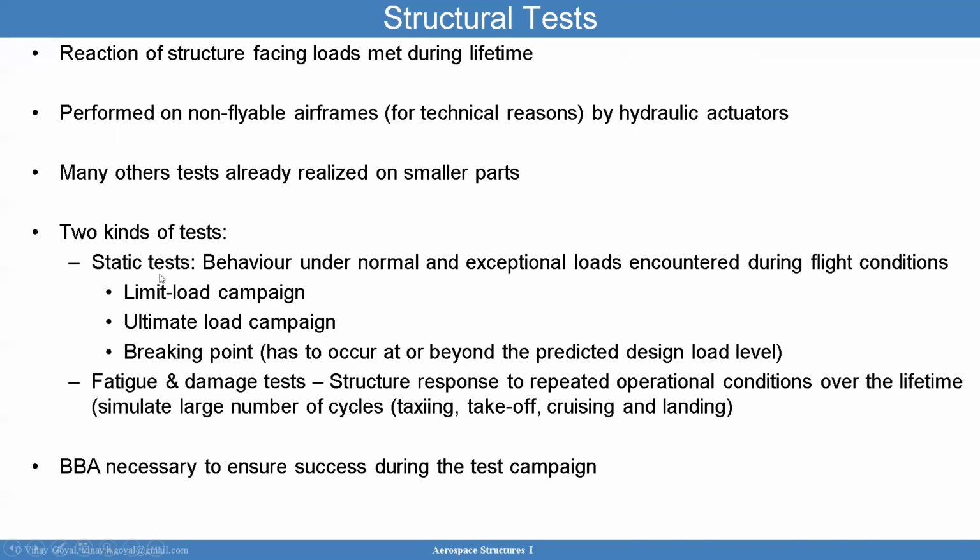And in this static test, you're looking at limit load conditions, ultimate load conditions, and the breaking point, which is the point at which failure could occur. And it has to occur above the ultimate load level. The fatigue and damage test, right there, what we're looking at is structural response to repeated operation conditions over the lifetime, simulating a large number of cycles, and that will include taxiing, takeoff, cruising, and landing.